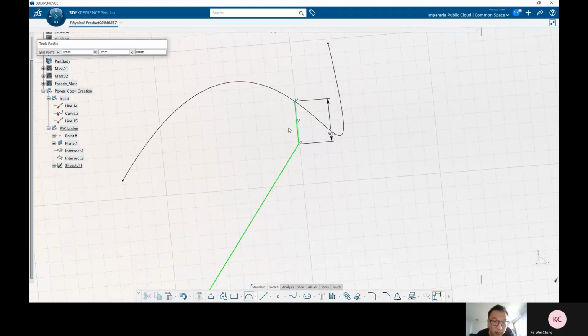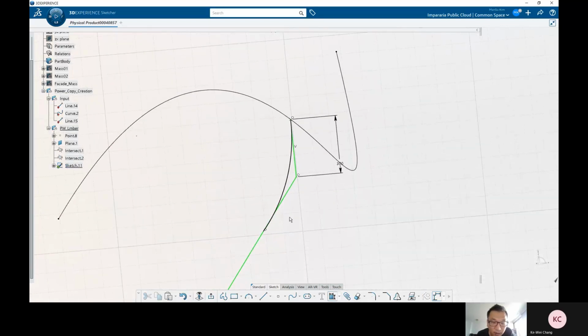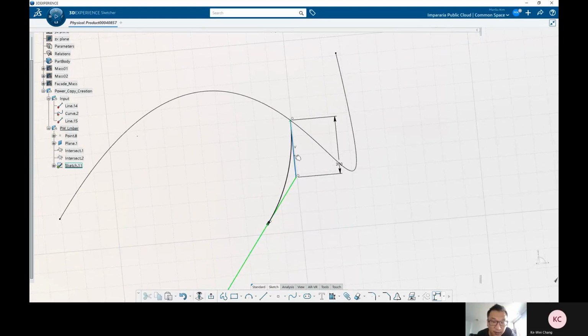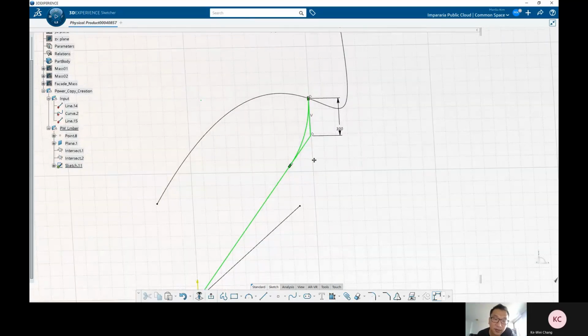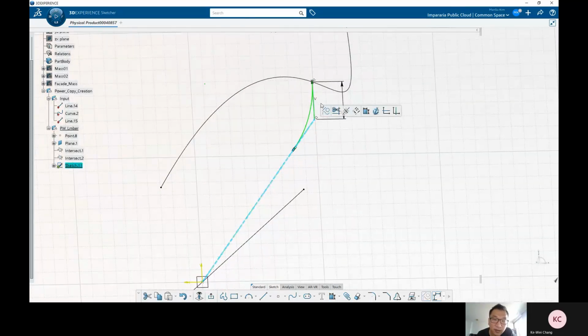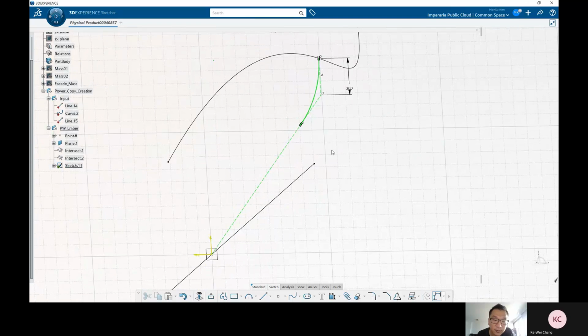And I will create the arc, a 3-point arc, 1, 2, 3, in these directions, and here's coincidence. Of course, it should be tangency. And on the other side, I also want a tangency, here for example. And this will be constructions. And I will add another line.